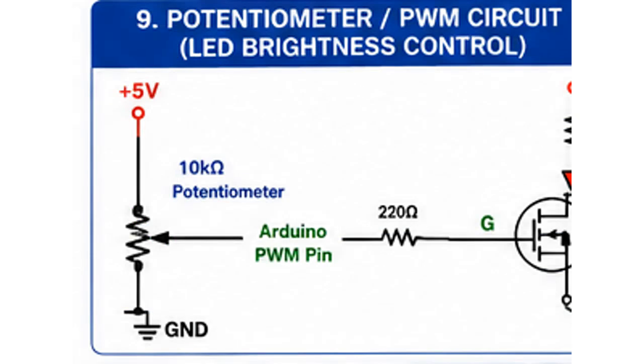How does a MOSFET compare with a bipolar junction transistor? A MOSFET is voltage controlled, a BJT is current controlled. In the steady state, the gate current of a MOSFET is only a tiny leakage current, whereas a BJT needs continuous base current to stay on.